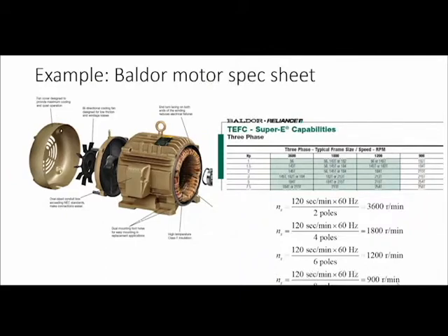Okay. Compressors, like compressors for air conditioning systems in your house, use AC synchronous motors because oftentimes they don't really care about much ability to tune them. They just want it to spin at a constant rate. They'll use AC synchronous motors. They're a very common solution, because they're simple. They're not necessarily simple in architecture, but they're simple in the way they operate.